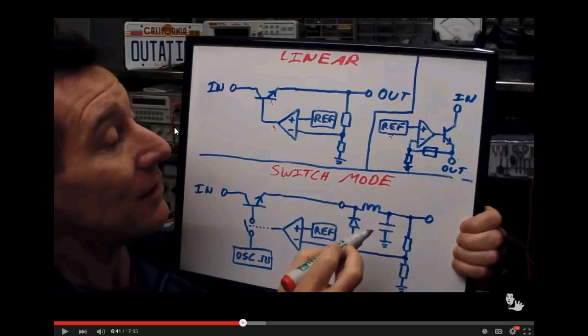What we do on a switch mode power supply is we bring it in, we don't have a transformer. The transformer's not first. We bring it in and we rectify it right off the bat. Then we filter it. Then we run it into a switch circuit. Then we run it into a transformer. But the transformer is controlled by a switch circuit. So we have a switch circuit right here that's coming in and oscillating the transformer. And the transformer does the same function.